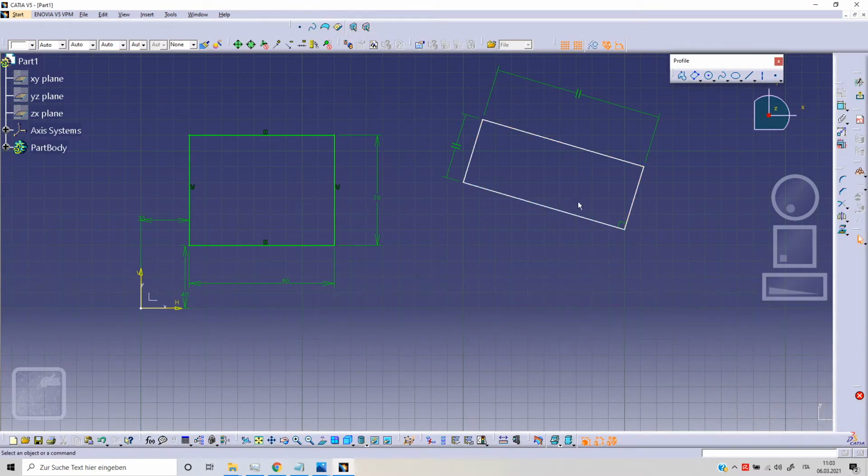To fix the position of our rectangle, we need to specify, for example, normally with this height, this base, the position of a particular point, for example our first vertex, this and this, and we need to specify this orientation, this and this, and now we've got an isoconstraint sketch.